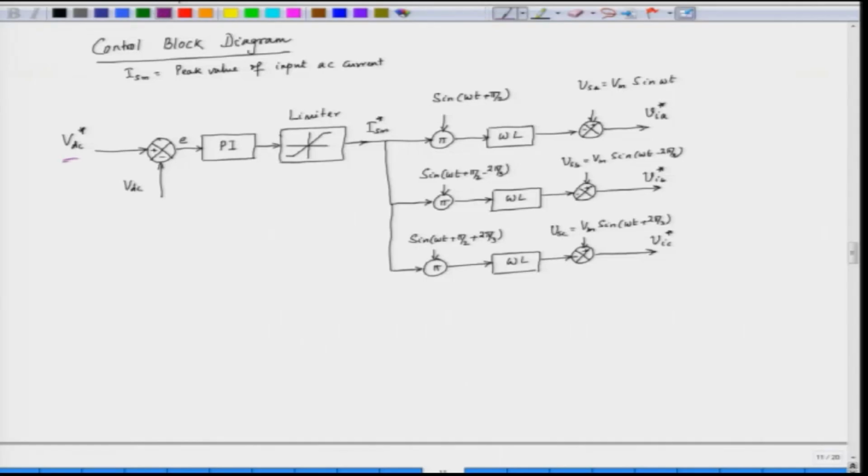So, when converter 1 is triggered, the input currents are controlled, and the objective is that we have a closed loop control by which we maintain the DC link voltage constant. With the change of the motor operation, the DC link voltage is automatically sensed and the current is given as ISM.